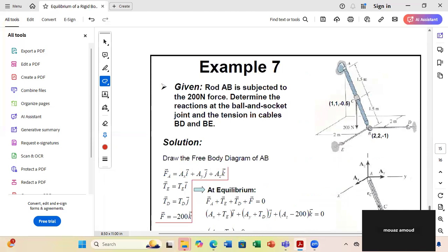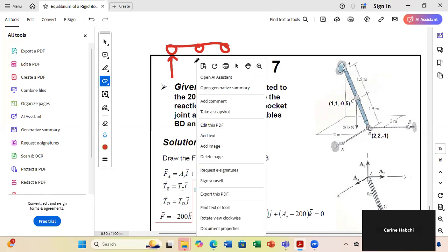Doctor, are partial and improper the same thing? No. Improper means the number of equations equals the number of unknowns, but the selection of the type of supports is not good. For example, if you put 3 rollers, you have 3 unknowns and 3 equations, but can you ensure equilibrium if you have a force in the x direction?